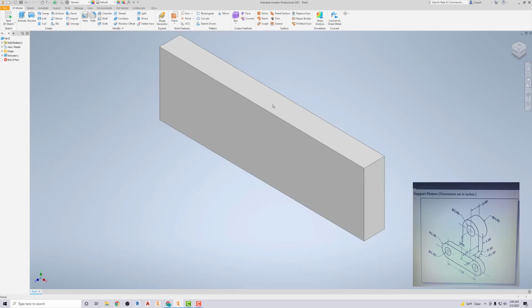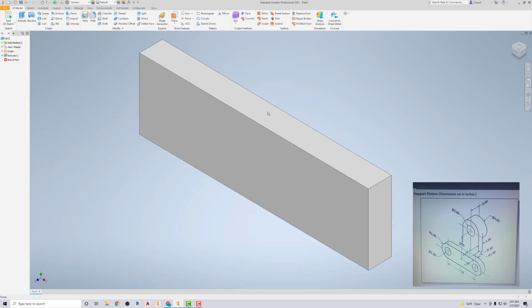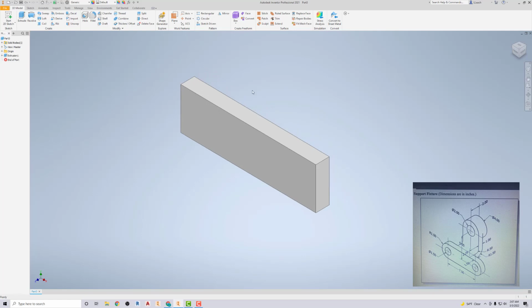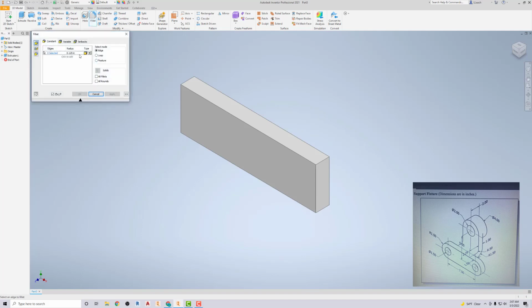All right, so I know you're like, dude, there's circles on each side. There's not a block. So what I'm going to do is use the fillet, and for my radius, that has a radius of 1.5. And then for my edges, I'm going to pick where it says 0 selected. I clicked on it. I'm going to select these edges on this block on each of the 4 corners. That rounds them off nice and hot looking, right?